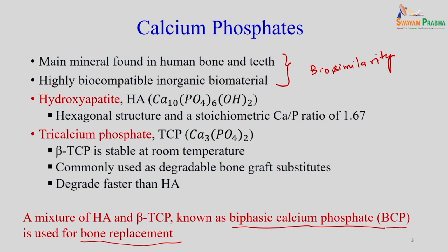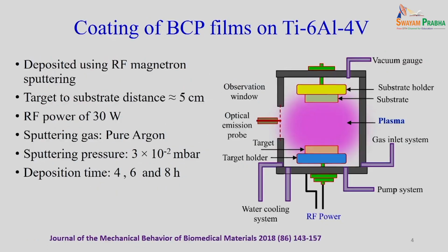So, here we will try to apply the physical coating, particularly we are more interested in hydroxyapatite on the titania surface. So, why titania? Because titania is already being applied for bone tissue engineering, especially for bone implants and dental implants.